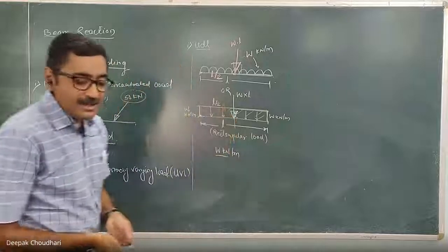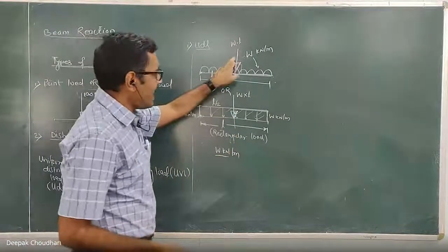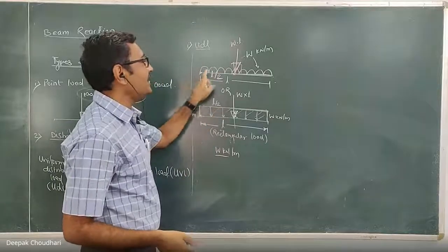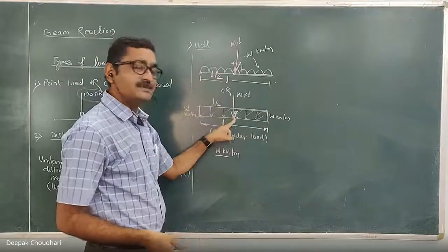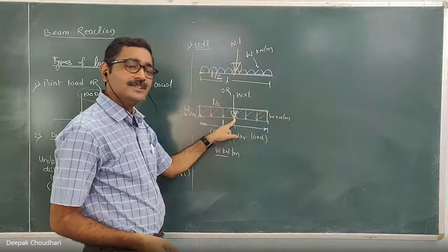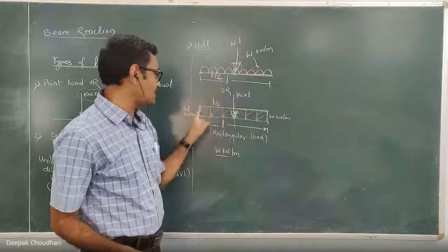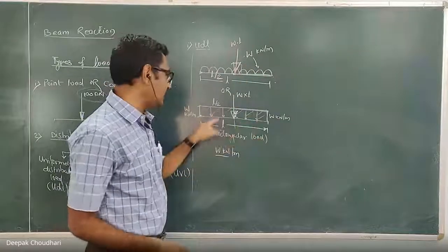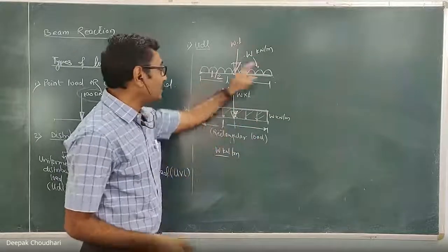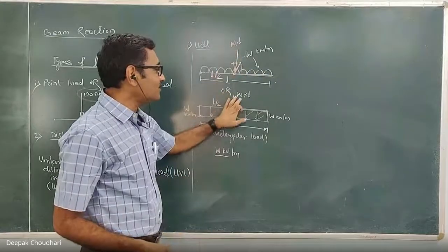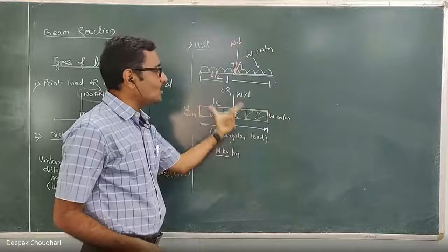So remember the equivalent point load. यहाँ पे देखो या तो यहाँ पे देखो. The equivalent point load for the UDL acts at the midpoint of the length over which it is spread, directed toward the base of that semicircular pattern, or directed toward the direction of that loading, perpendicular to the base. And the magnitude is equal to the product of the intensity and the length over which it is spread.